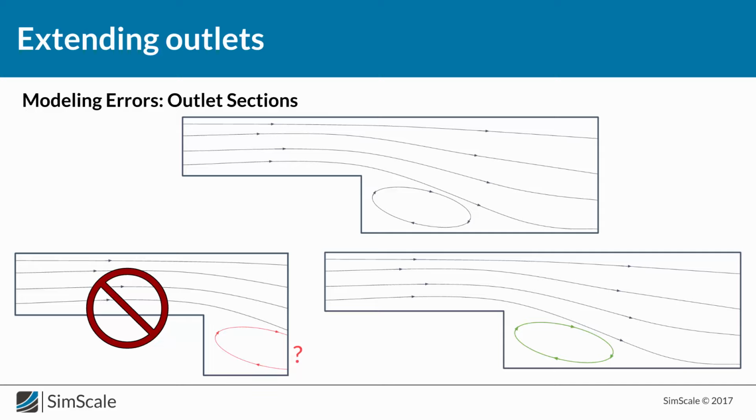Both of those actions will mean that we are making the domain bigger, and we are creating additional, not physically correct extensions to the inlets and outlets. But that is okay. Since we are introducing a proper flow into the area of interest, that's the first thing, and we will disregard any phenomenon that is happening after our actual outlet or actual limit of the flow.